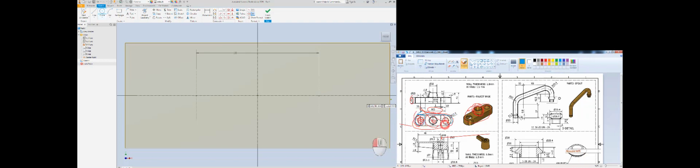This blue outline is the slot part. First this one and the second one. And I will make two lines onto it. Also the second line on the bottom side. And make tangent conditions with these two lines to each line.